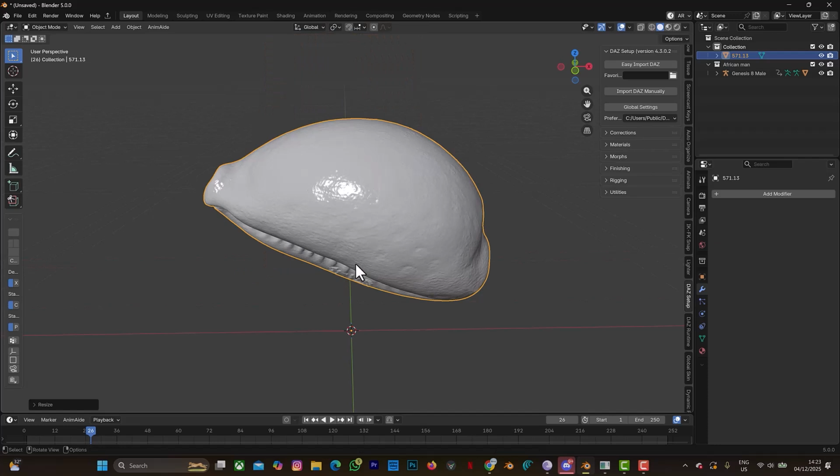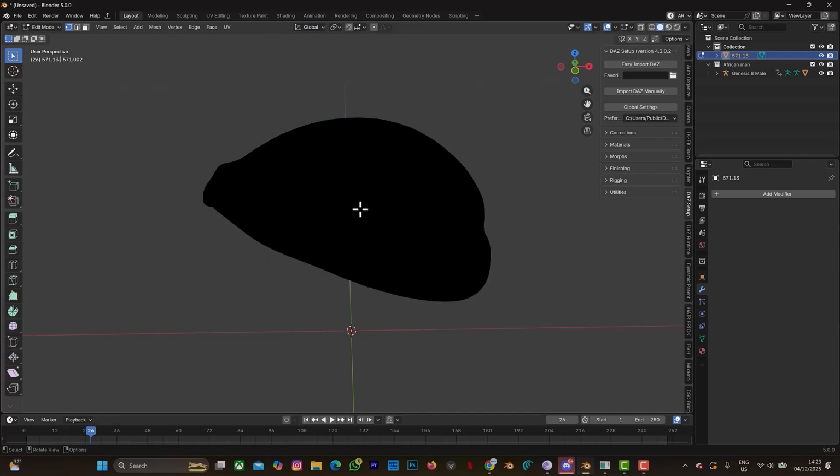So the next thing we're going to do is to check the number of polygons, or to see how it looks in edit mode. So I'm going to select Tab. This shows that we have a lot of face count on this model, which means it is not good for us to use this on CLO3D because it is going to crash if we have something like this. Imagine using multiple of this particular model as top stitch on CLO3D. Your system might get fried.